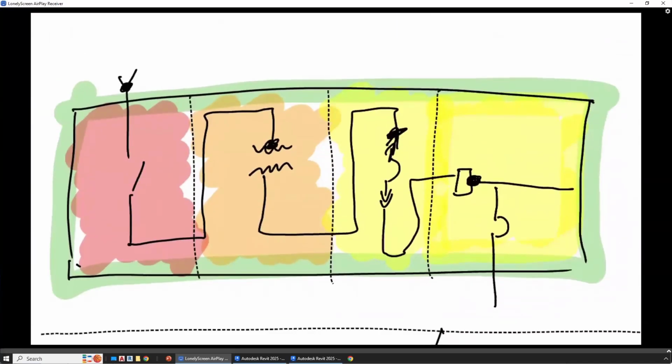It depends, I guess, on how often you do that. If it's something that you do regularly, a switchboard with an ATS embedded would be a useful family to have if you're going to use it on a couple projects. If it's just a one-time thing that you're only seeing once, I would just do a transfer switch and a switchboard, because it's going to be way simpler and you just move on with your life in the project.